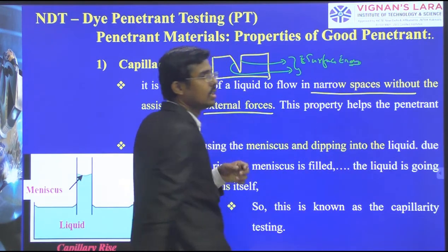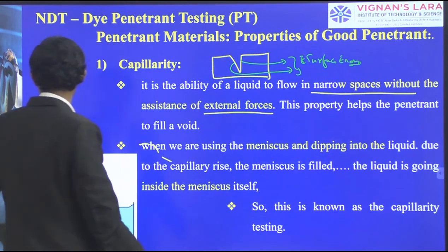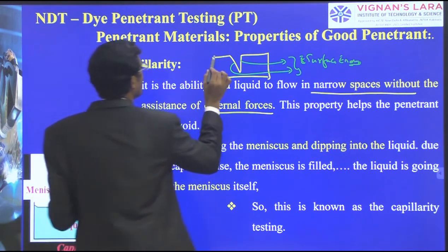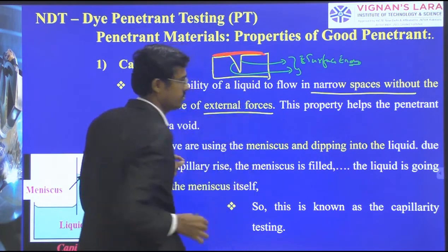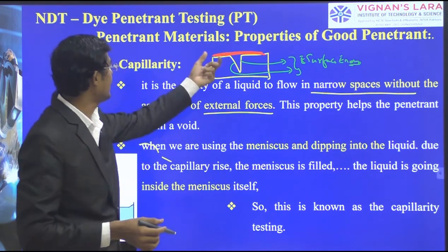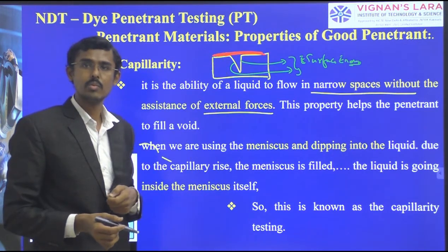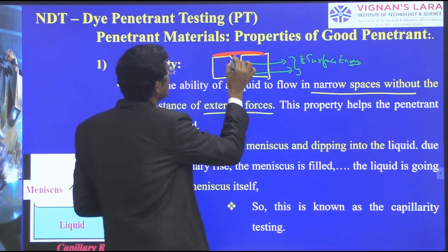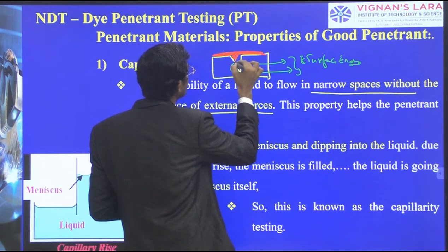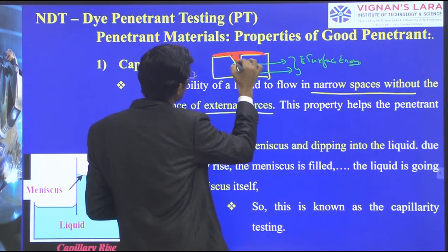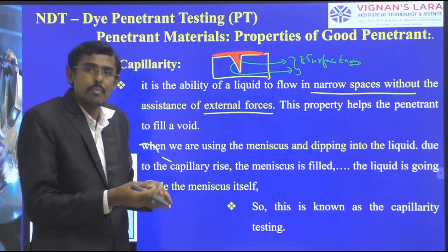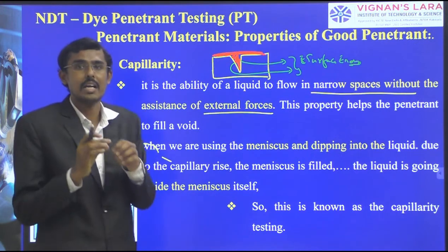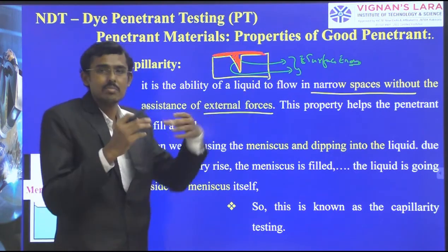Surface energy. When I am pouring this penetrant material at the top, the surface energy attracts the liquid automatically, and therefore this penetrant material fills here. This process is called capillary action, which happens due to surface energy.